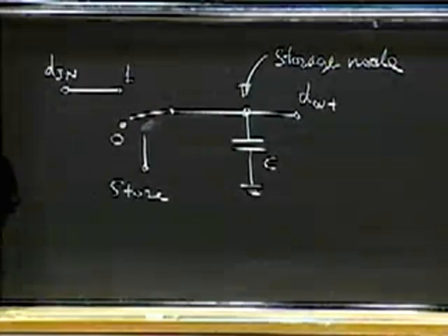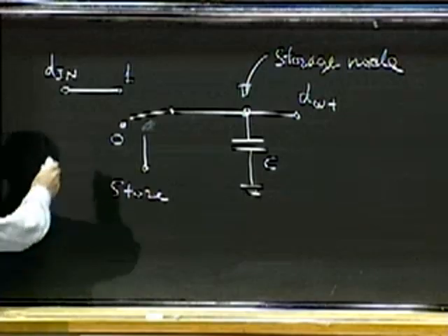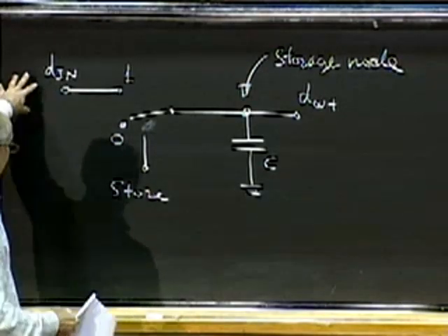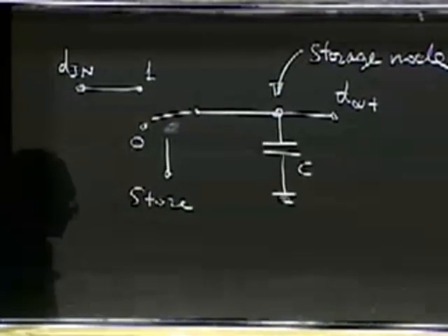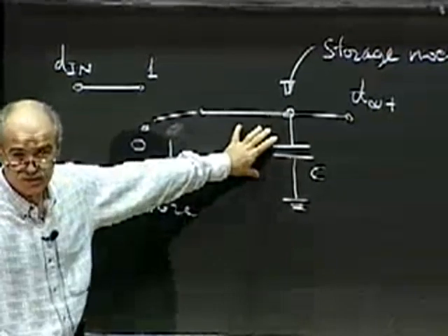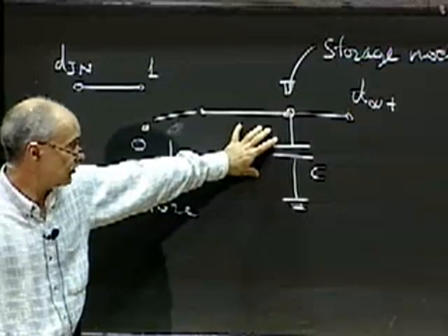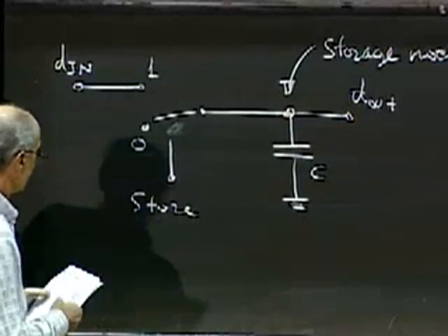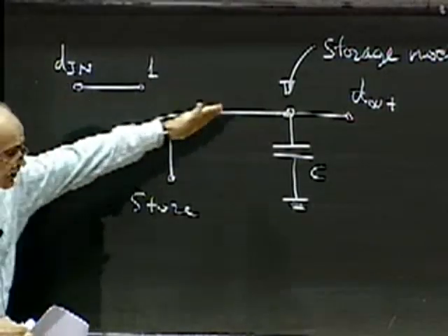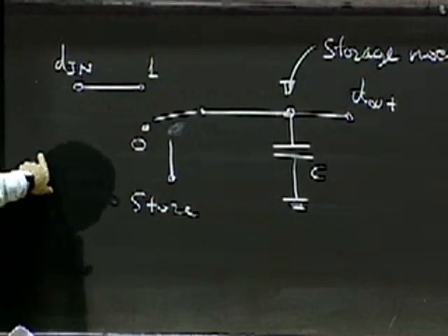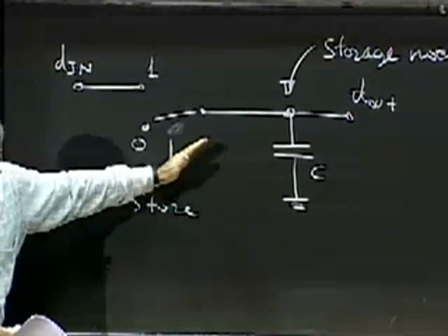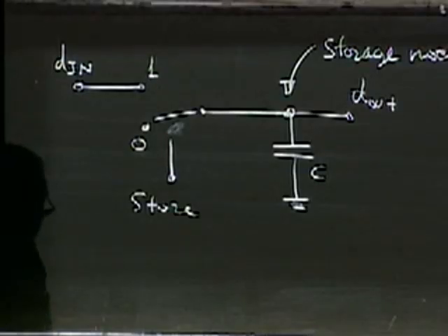Okay? What are we actually storing in this case? Let's suppose that this voltage here is 5 volts. I flip the switch up to 1. Then I flip it back down to 0. So what's the voltage on this capacitor here? 5 volts. Okay? If the input was, now the capacitor is at 5 volts. I put D in to ground. Okay? Flip the switch back up, then back down to its non-storing condition. What's the voltage on the capacitor? It's 0, exactly.